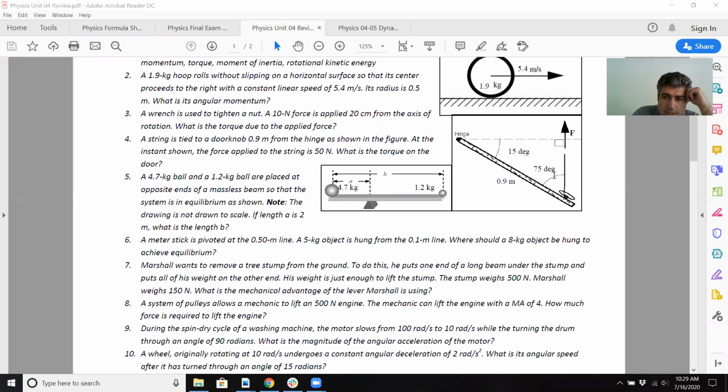So this is the force you're applying, right? And you want the force to be, it's a little tricky here, and you can go about this a couple ways. You want your force to be perpendicular to the radius or to the lever arm. That's how torque is always applied. That's really the force we want, the perpendicular force. Now, if you do 15 degrees, that's obviously going to be 15 degrees because that was 75. And your force here is 50.